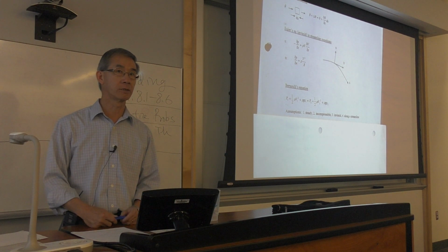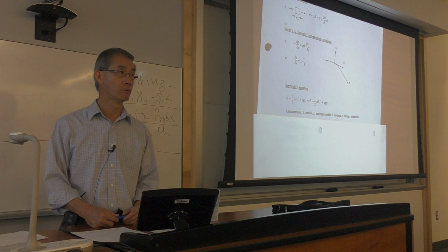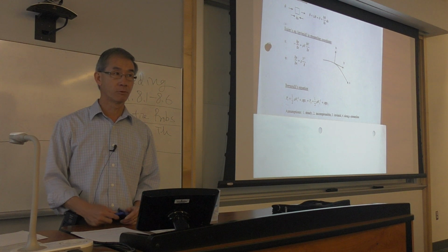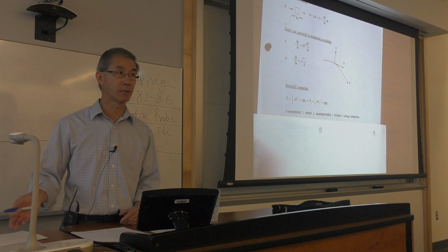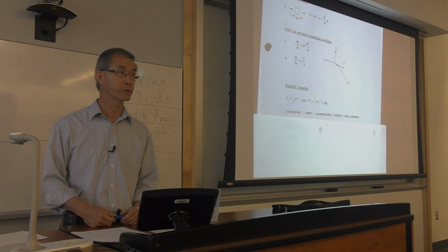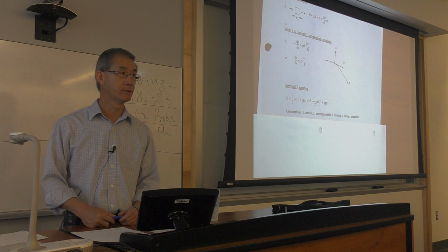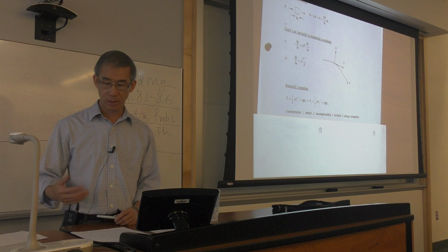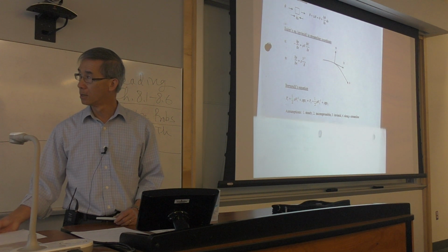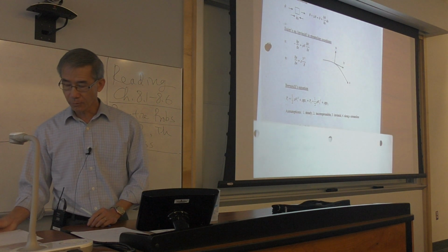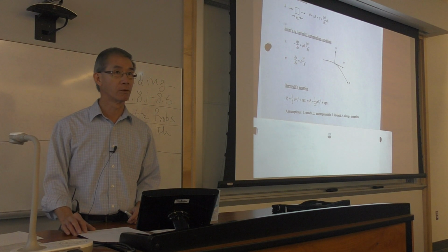No forces are involved, meaning I don't have to deal with momentum. But you will be tricked if the assumptions cannot be met within Bernoulli, and don't use it, just like SP1. Think of other means to solve the problem. Is that clear? And heat addition or energy has nothing to do with Bernoulli. It's not an energy equation. So I'm trying to stress all this basic and fundamental. Okay, so that's it for Bernoulli, which is chapter 3. A lot of time has been spent on it. Questions?